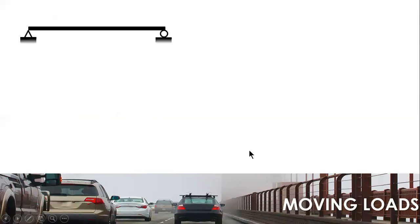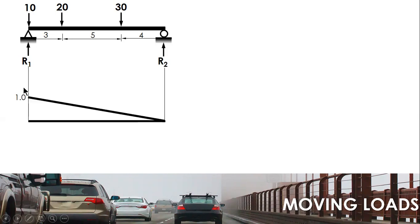For shear, draw the influence line of the left support. It is 1. Then place the loads, 3, 5, 4. The slope is 1 divided by 12, times the horizontal distance, 9.